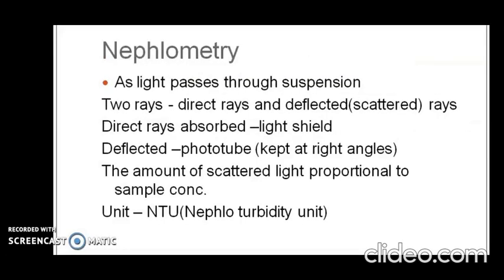Nephelometry is a more sensitive instrument for measuring scattered light. In nephelometry, the light sensing device is arranged at right angles to the scattered light. And the greater sensitivity of nephelometry is due to its measuring scattered light rather than residual and scattered light.